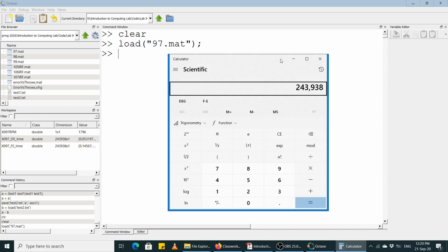So here our quantity of interest is the vibration acceleration, the acceleration of the vibration of a bearing, how quickly or how sharp or how strong that vibration is. And so one measurement of that quantity is one sample. Sampling rate is how many samples you take in a unit time, or how many measurements you take in a unit time. So these measurements were taken at 12,000 samples per second. These are the total samples.